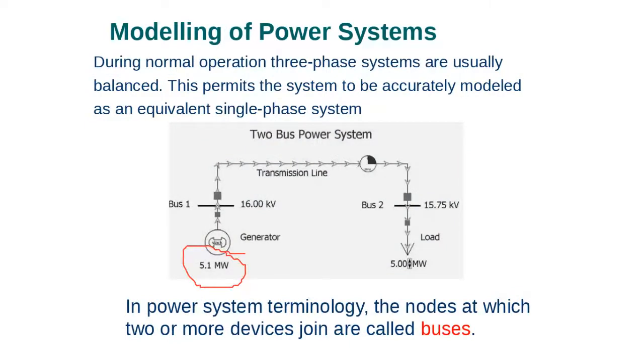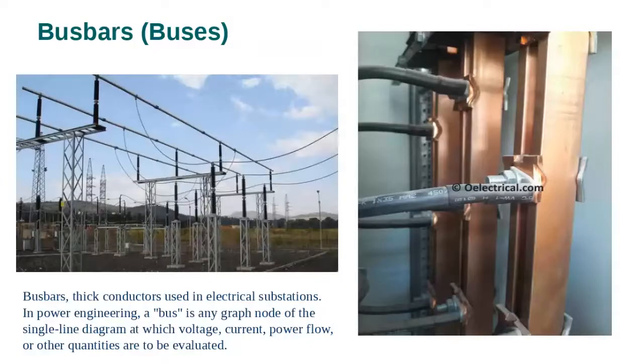The indicated power is three-phase power. So we don't write for one single phase and then multiply. The power is for the three phases, and the voltage is line to line. So please make sure that you understand the terminologies we discuss here.